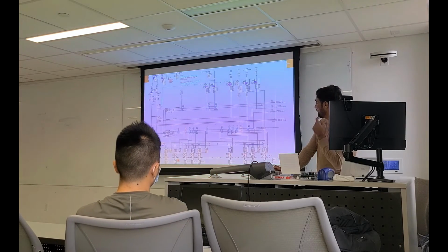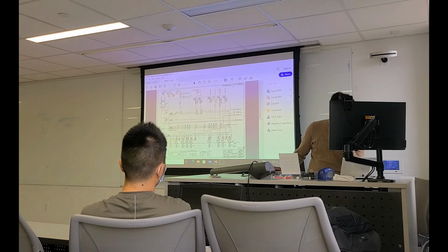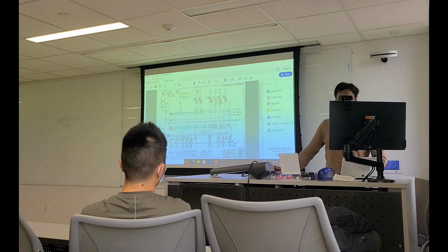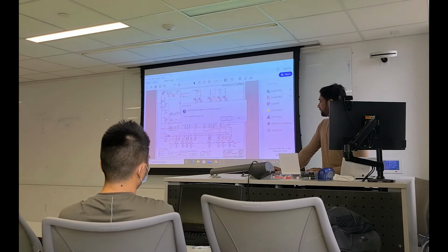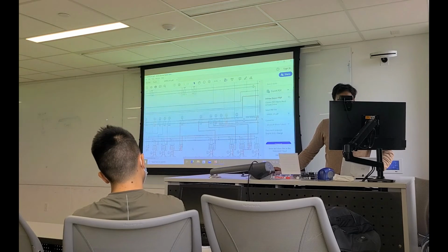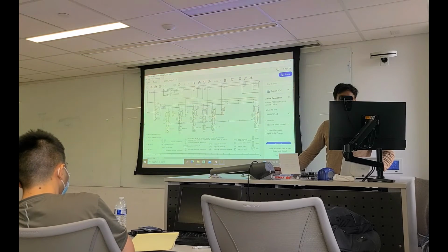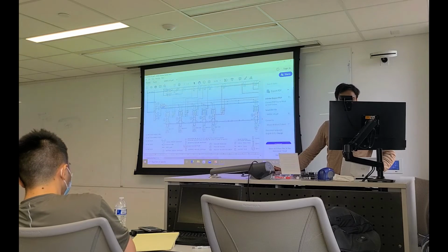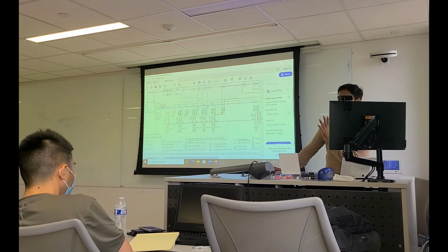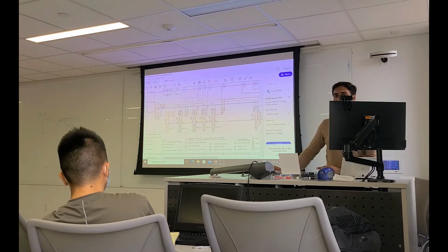Okay, and then this is the diagram. I think it is not clear, so I can show you a separate diagram. Yeah. Whatever I have explained, it is in this diagram. I have talked about the MO sources. So these are the MO sources, okay, metal organic sources. Wherever there are two MFCs, that means those are the double dilution lines. Okay, so we need double dilution lines for gallium, for aluminium.